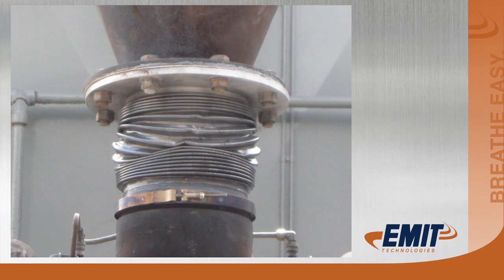Okay, this unit obviously had a big backfire. It stretched and deformed the bellows. Probably the deformation on the bellows itself wouldn't be a problem, but what we worry about is this particular one with this band clamp. This would be a Waukesha 7044 or 7042. With this bellows, there's a flange down here on the bottom, and we'll see those get deformed when you see a backfire of this magnitude up here. And they'll suck air in and cause a lot of grief for you.